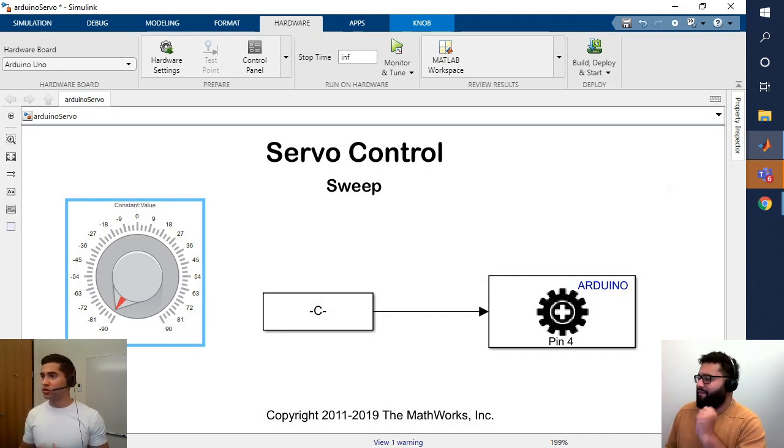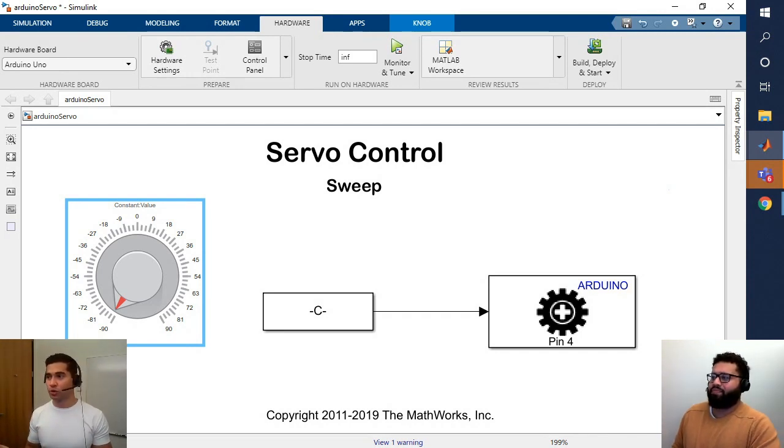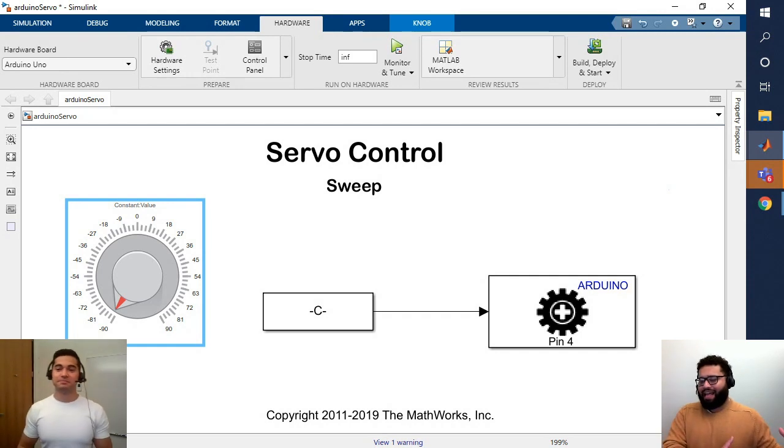There's a question on, could we do simulation of 2 different controllers like PID and fuzzy using a for loop? I guess you could. MATLAB allows you to programmatically control Simulink models. So you can go down to the point where you're adding blocks in, removing blocks out. So yes, if you have a for loop, you can add in a particular block or subtract a particular block, that's definitely possible. I recommend taking a look at the documentation for that.